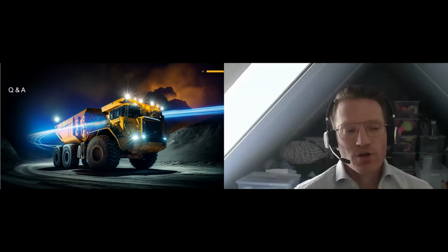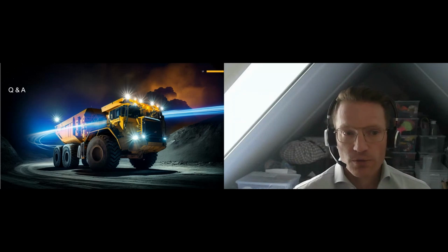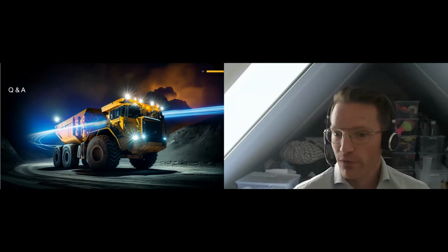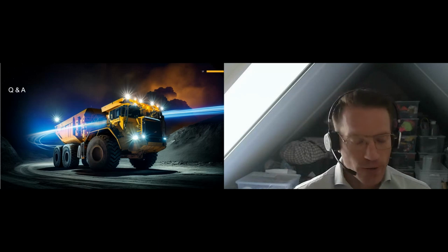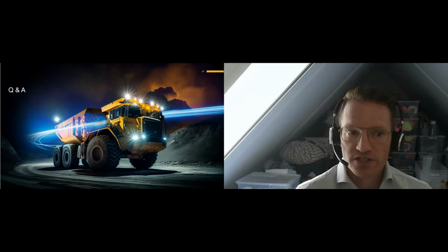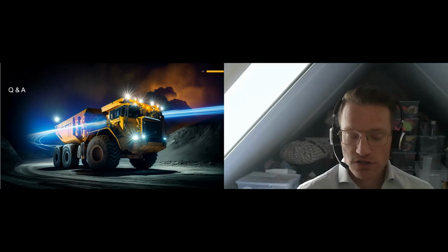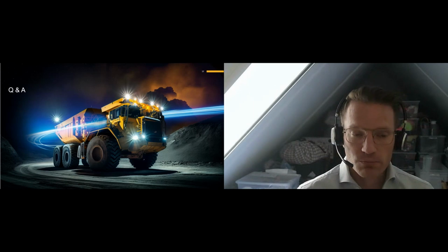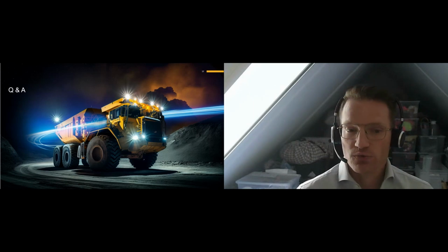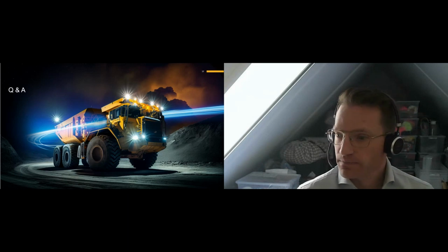Well, there's not really one answer to that question. We've done it for very big rigid trucks, let's say 100-ton rigid haulers, but we've also done that for really small 4x4 military vehicles. So I would say from 50 liters to 5,000 liters, all those tanks can be optimized. What we do see is that where footprint is important, it typically has the most advantages. Typically off-highway mobile equipment, but also renewable energy, wind turbines. Footprint is really limited in a wind turbine, so there also tank optimization is really beneficial.